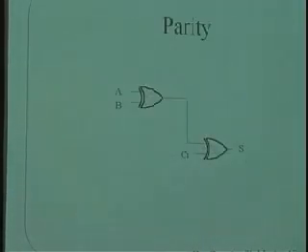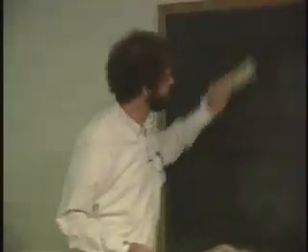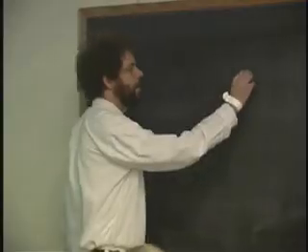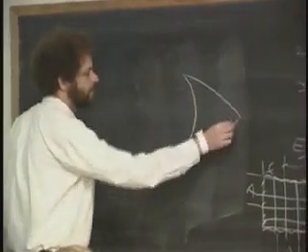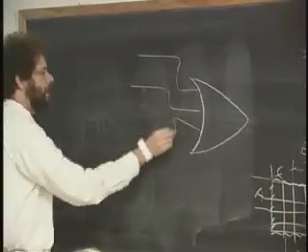All righty. So parity, however, does not mean that you can't build a circuit to simplify things anyway. So what am I really trying to say here? Sum of products form is effectively saying that I'm going to build my logic in the following way. There's going to be an OR gate, and feeding into that is going to be a bunch of AND gates.